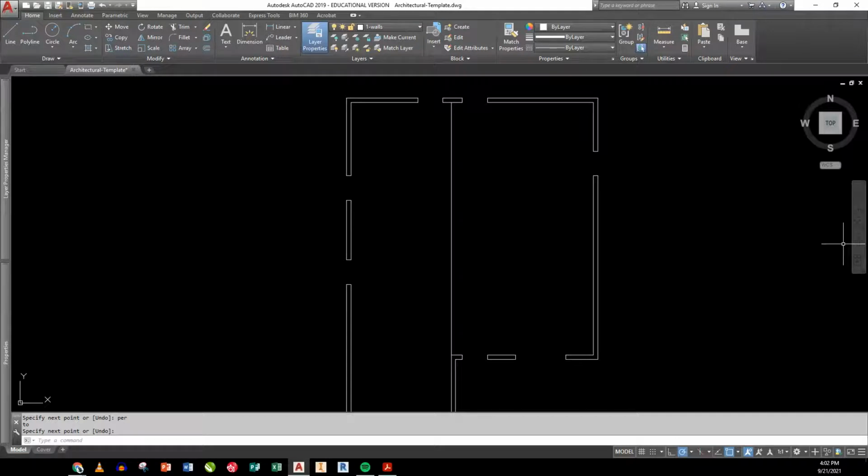This line right here, the way it's drawn on the plan, is actually not a true bearing wall. It's just a divider wall. It might bear a load, but this house is only 30 feet across. A normal roof truss can span that. And so honestly, it doesn't need one. It's for a crawl space or slab on grade construction. So I'm actually going to offset the 3.5 inches that is the interior wall right here.